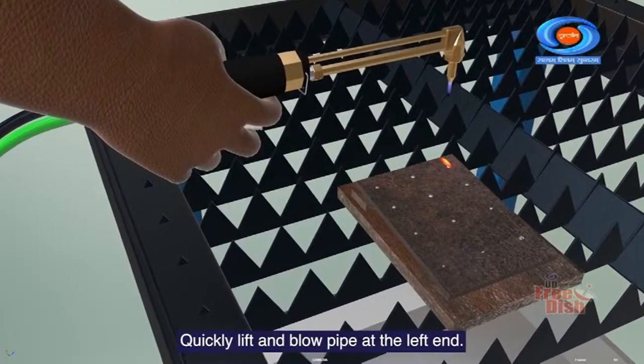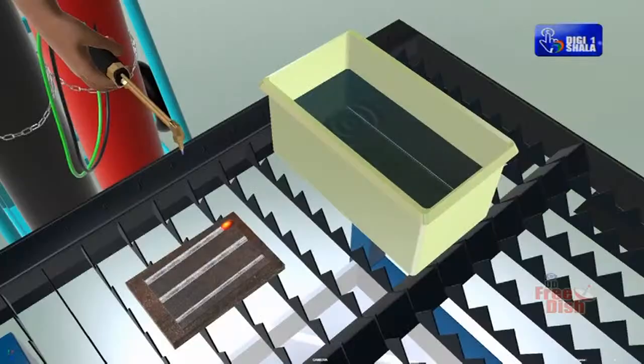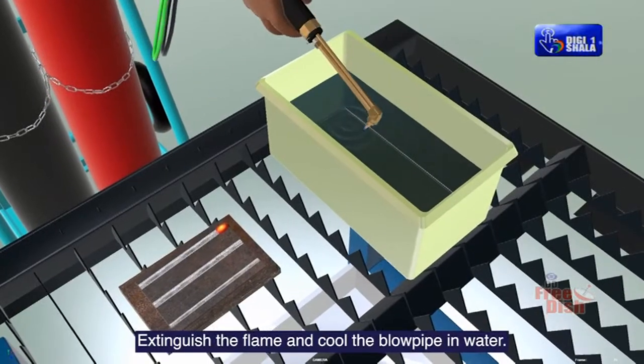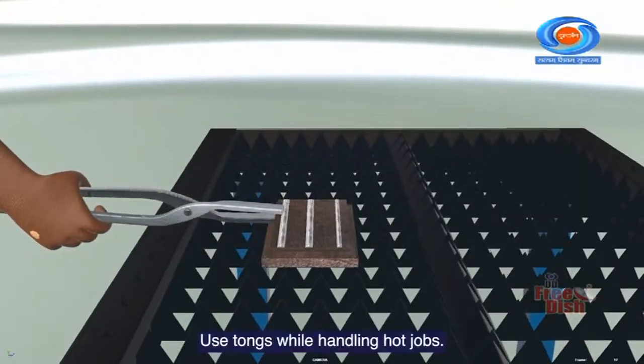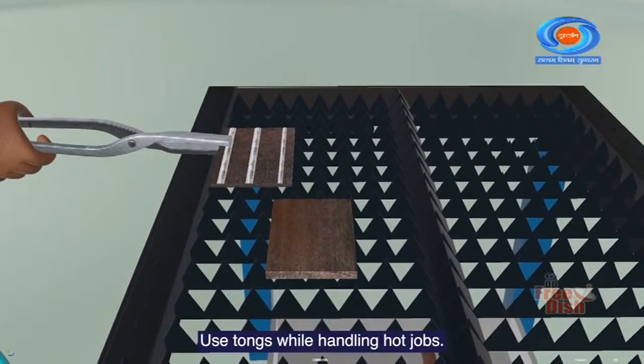Quickly lift the blowpipe at the left end. Extinguish the flame and cool the blowpipe in water. Use tongs while handling hot jobs.